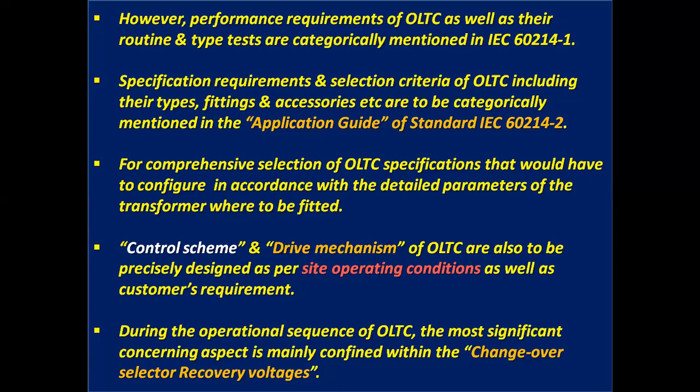Control scheme and drive mechanism of OLTC are also to be precisely designed as per the site operating conditions as well as customers' requirement. During the operational sequence of OLTC, the most significant concerning aspect is mainly confined within the changeover selector recovery voltages.